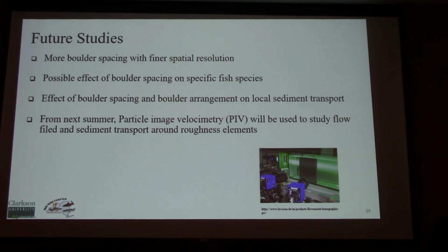And the effect of boulder spacing and boulder arrangement on local sediment transport, bed load and suspended, that can affect water quality. And hopefully from next summer we will have a particle image velocimetry PIV system. With that we can study sediment transport and flow field around the roughness elements with very high accuracy.